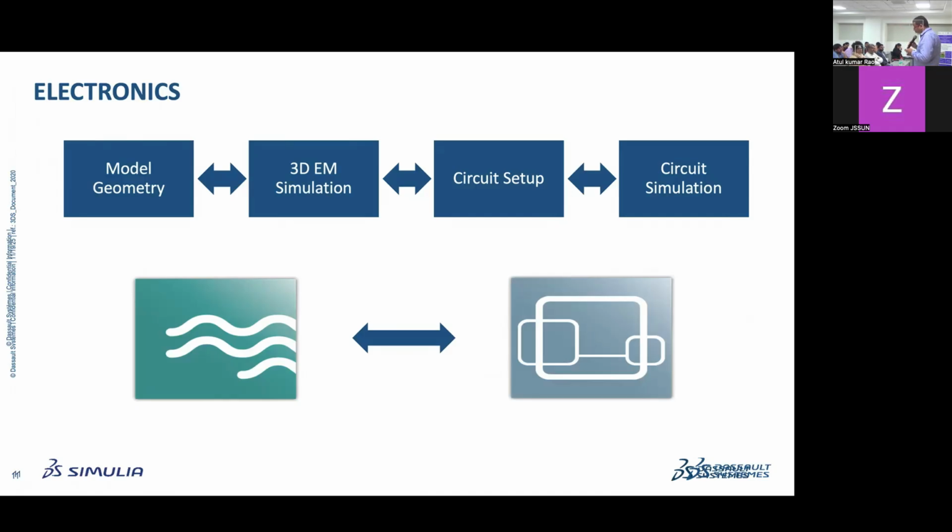And especially in the automotive industry, this is very critical because you have lots and lots of power converters: step up, step down converters, buck converters, boost converters, synchronous, asynchronous converters, and so on. So you would have to characterize that before your system gets certified. And there are always standards already designated for your CE emission limits. Your device will not be cleared otherwise.